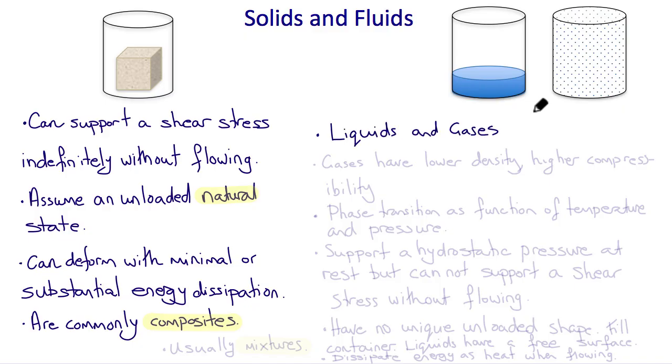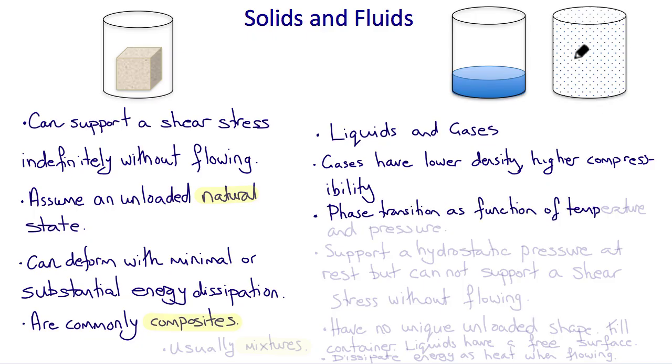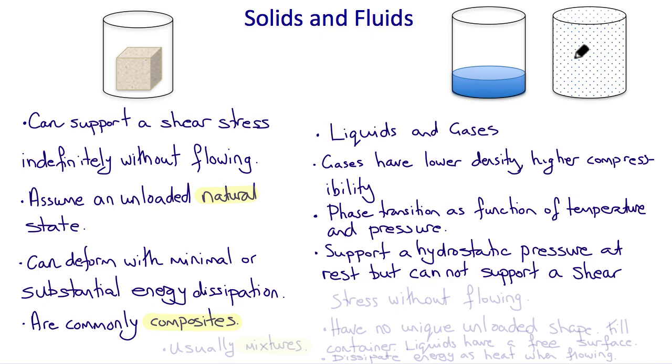Fluids are liquids and gases. Gases have lower density and higher compressibility than liquids, and there's usually a phase transition as a function of temperature and pressure from liquid to gas and gas to liquid. They can support a hydrostatic pressure at rest, but they cannot support a shear stress without eventually flowing. They have no unique unloaded shape, so they fill their container.